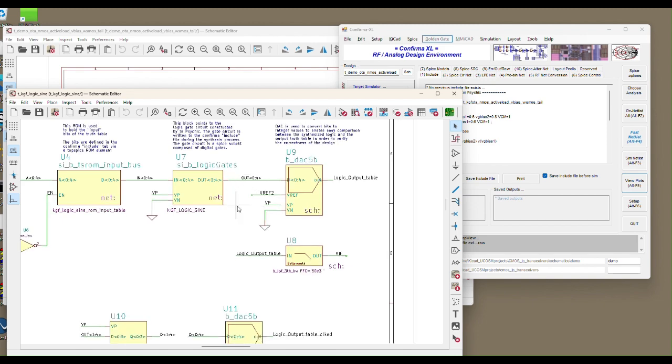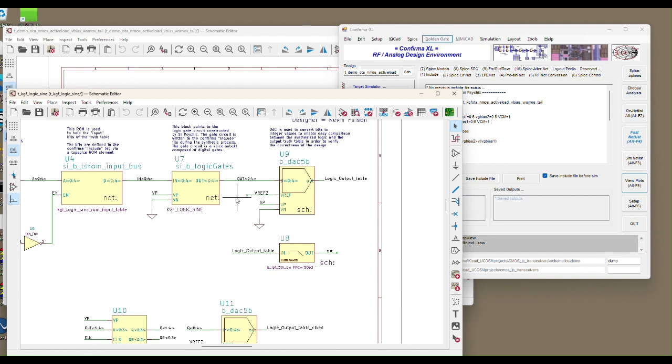So as I recall, I think what we're trying to do is generate a sinusoidal output wave using a D to A converter, and apparently there's some ROM logic here that encodes the D to A input, so we get a sine wave output. Then that sine wave output, which has quantization error, is input to an analog filter, and so that should remove all that and give us a smoother looking analog waveform. So let's take a look at that.